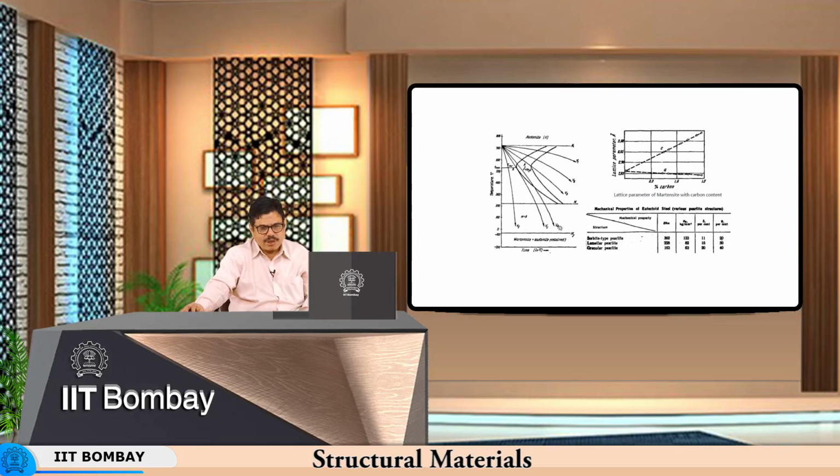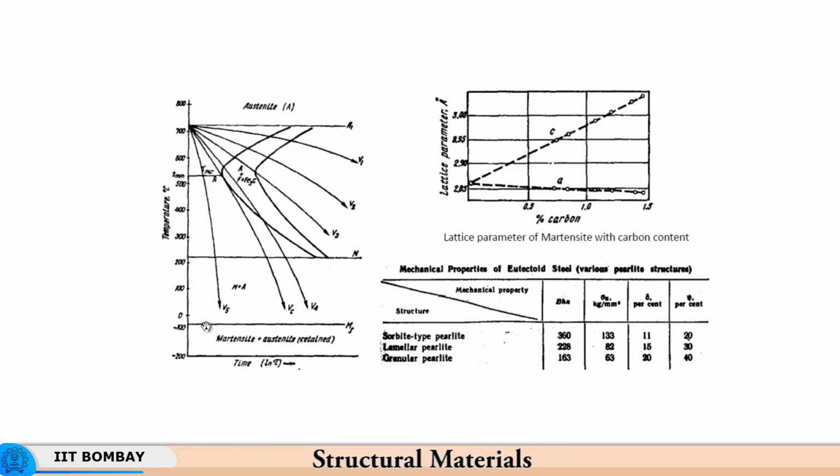So, here you will have about 3 phases. You will have iron carbide, you will have martensite and some retained austenite at room temperature. If you were to cool it further down, as we do in case of cryogenic heat treatment, which we will see later, you will find that the entire austenite would have got transformed. So, this retained austenite would have entirely transformed to martensite, and then you will have just martensite and cementite over here. Now, martensite formation is a completely diffusionless transformation.